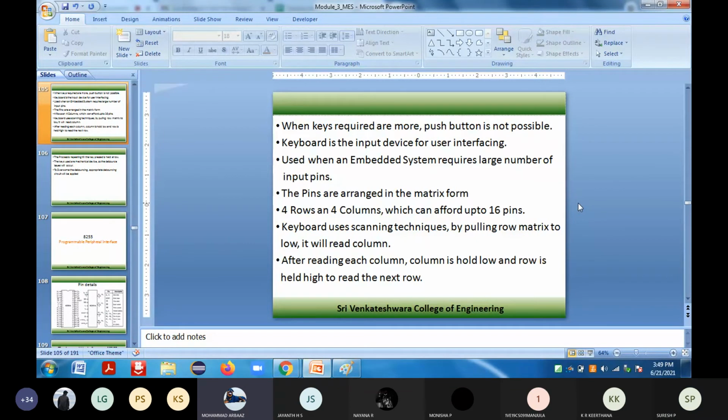Sorry, we use the SR latch to eradicate switch debouncing. Yes, only the SR latch is used. For what purpose is it used? So that it should not oscillate between the high and low states, right? For that particular purpose, you have used the debouncing circuit.